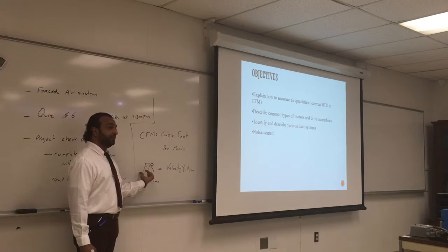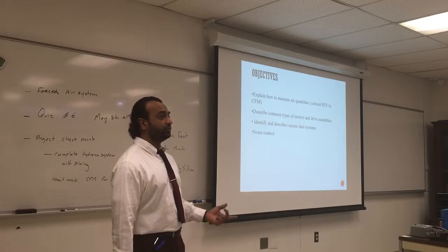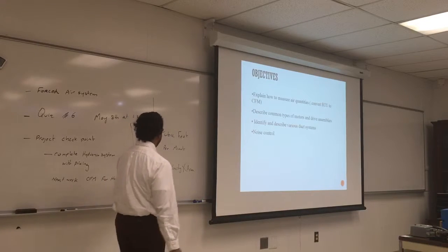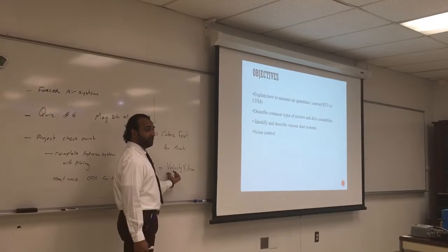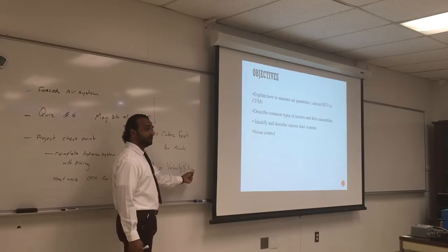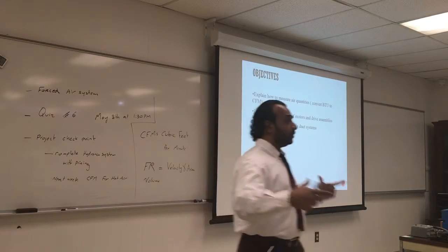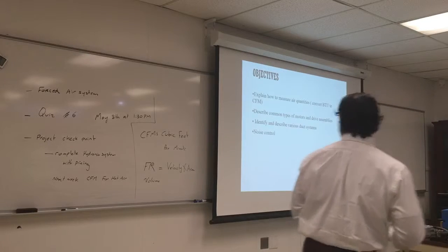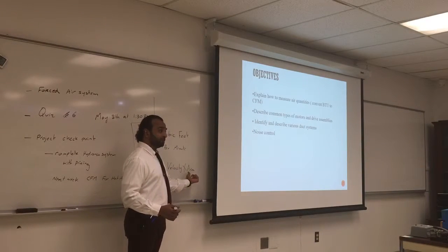So if we want to maintain the same flow rate, you would decide that this room requires 300 CFM or 30 CFM. I want to maintain that flow rate. I can control either the velocity and/or the area. So either you will have a bigger register or a slower velocity. If you have the flow rate with a smaller area, with high velocity, what will happen?